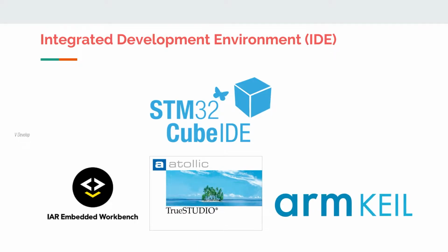The advantages of STM32CubeIDE are that it is free software and it comes with CubeMX, which is a GUI tool to easily configure the pins and ports in the microcontroller. For a beginner, I recommend using CubeIDE. We can download CubeIDE from the ST website itself.